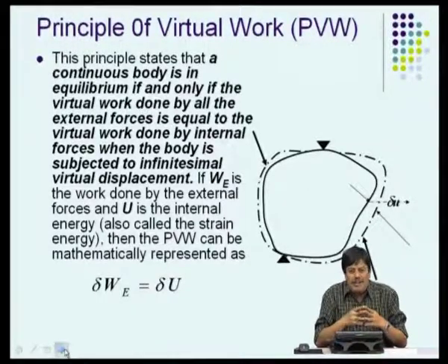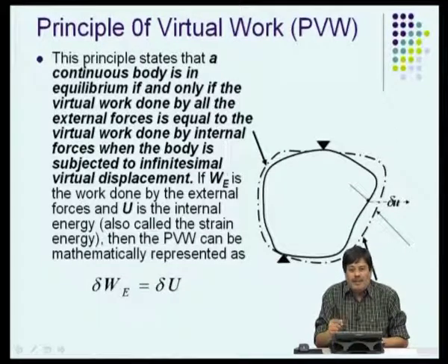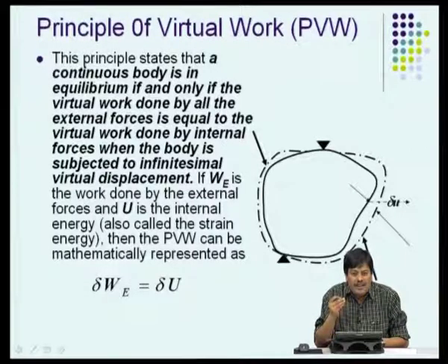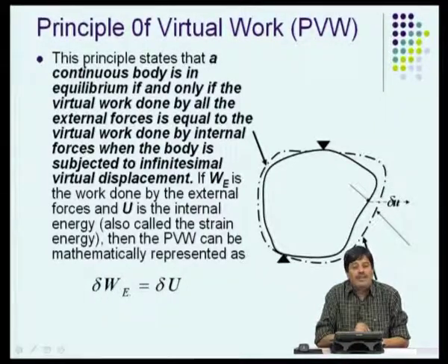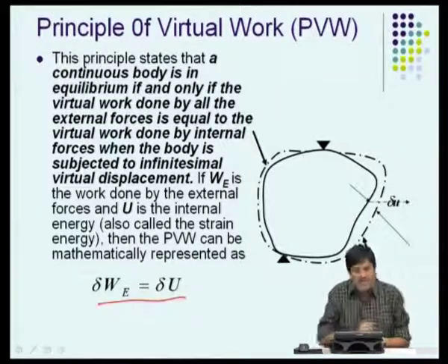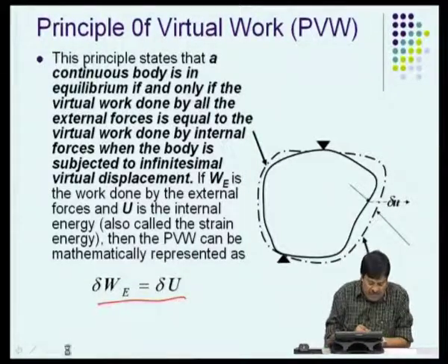If you have a body having certain constraints, and if you give a virtual infinitesimal displacement to certain parts of the body, and the body deforms in a manner where the boundary conditions are satisfied, then if that is the case, the total virtual energy due to external force is equal to the virtual strain energy. This is the heart of my FEM principle. So, let us actually derive this.